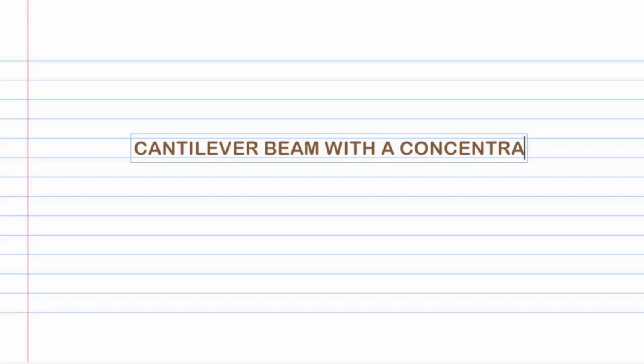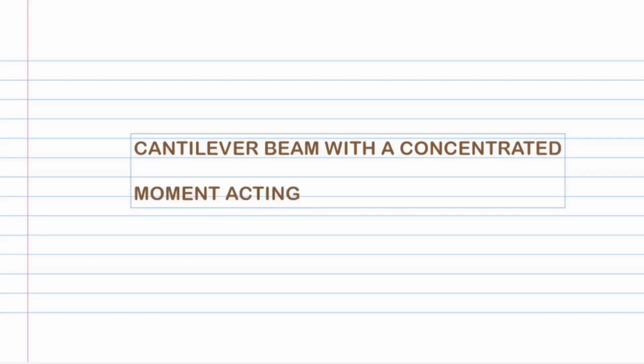In this lecture, we shall analyze the cantilever beam for the shear force and bending moment values over the length for a concentrated moment acting at the tip. Let's draw a cantilever beam with fixed end A and free end B. Let us show a clockwise concentrated moment M acting at the tip.